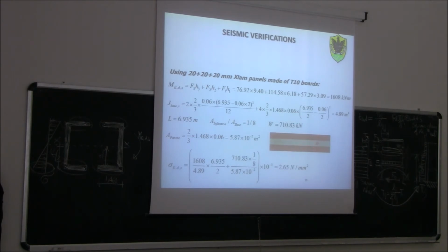You can add it if you want to be rigorous, but you will find that it's very small compared to the other one. In this case, the transportation bending moment will be related to the square of a length which is, let's say, 10 plus 10, 20 millimeter, while this other transportation moment is related, instead of 20 millimeter, to 3 meter, which is 1,000 times more. So for this reason, just ignore it. But strictly speaking, you should keep it. Yes, you should put it. But you will find that it's negligible.